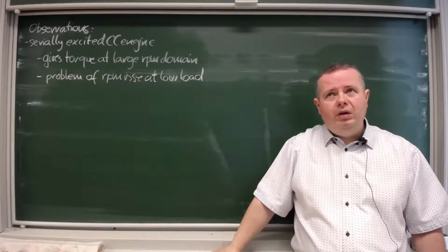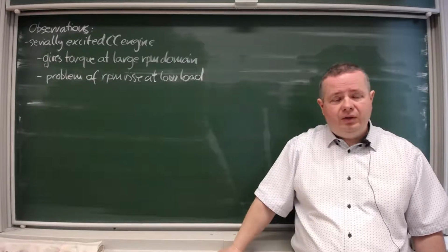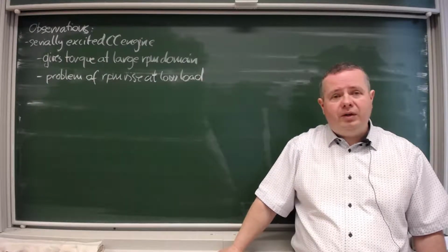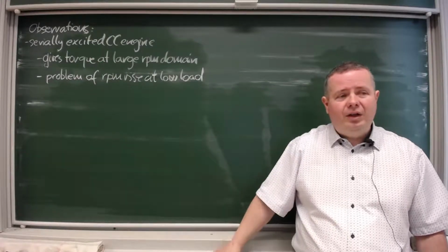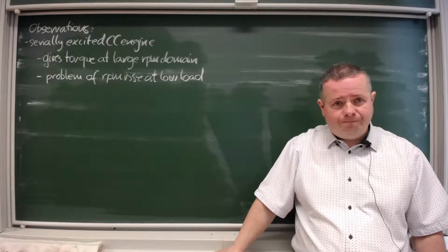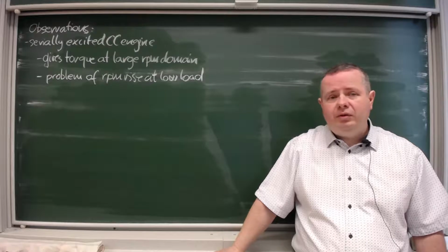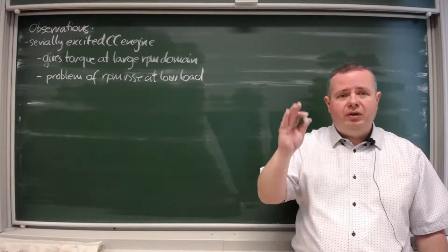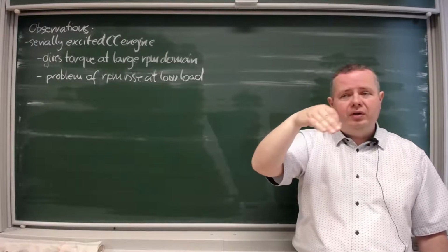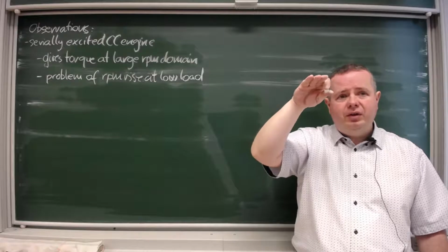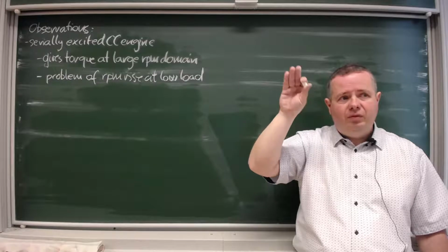Above a certain speed, the commutator's parts tend to go in radial direction, and the commutator can explode. And not only explode, but also in the commutator you get a certain radius level for the top of the wire sheets, and one level below for the insulating sheets, if you were observing the sketch.